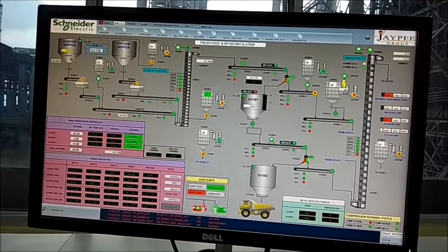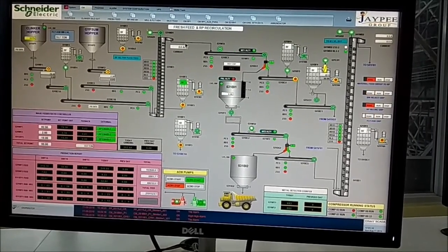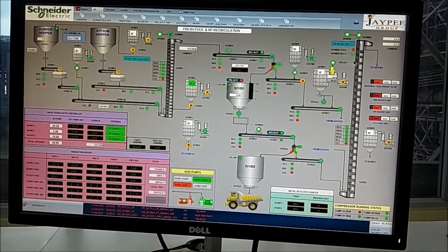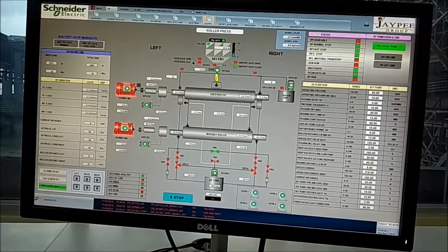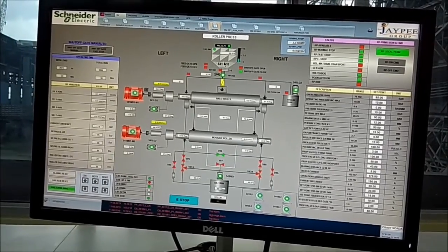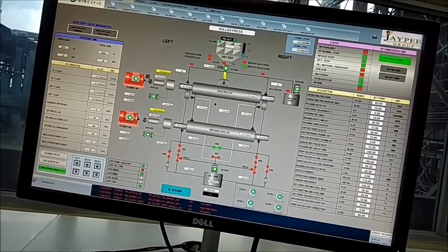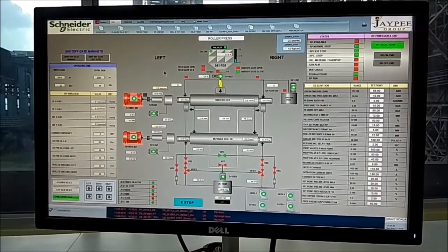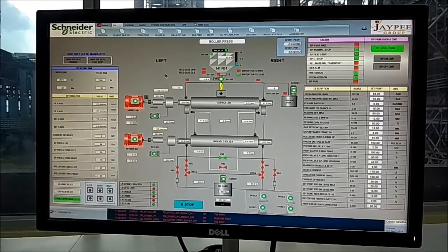So this is a pre-bin. Now this is a pre-bin, you can see. So the material gets collected in the pre-bin, all coming through the elevators. After the material gets collected, you can see there's a gate over there, shut-off gate. So according to the requirement, the material comes to the shutter gate, and then the shutter gate is controlled from here, that how much percentage has to open.